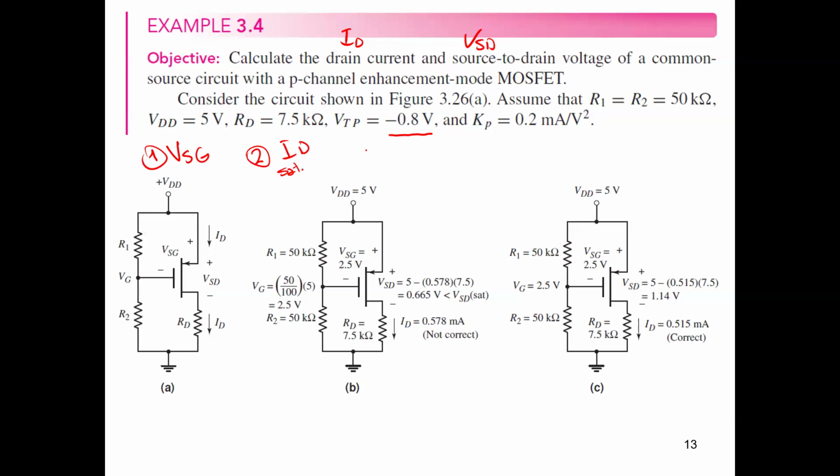Step number 3, use the circuit equation to get VSD and compare. Compare with what? Compare with the transition point, transition of the saturation.